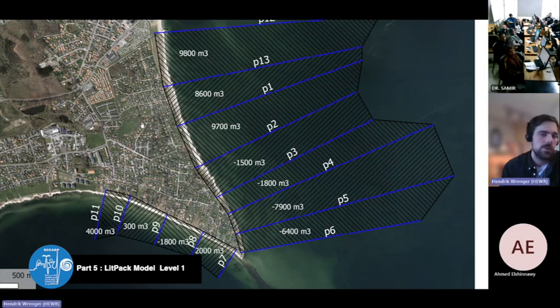modeling all these groins here, you say, okay, we have actually a revetment. So we have a structure along the shore where the effect is that it stops the shoreline erosion due to that revetment. But then you need to find the parameters to model that revetment, and that would mean that you somehow need to have some knowledge of the exact long-term effect of these groins here to then compare that with the long-term effect that you end up modeling with a revetment in your model. And we simply didn't have that information.